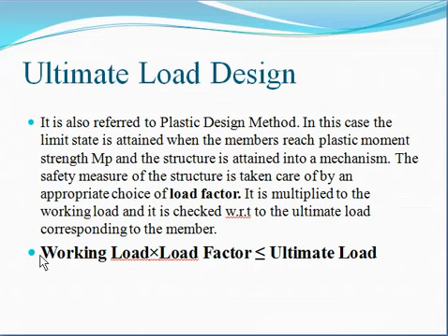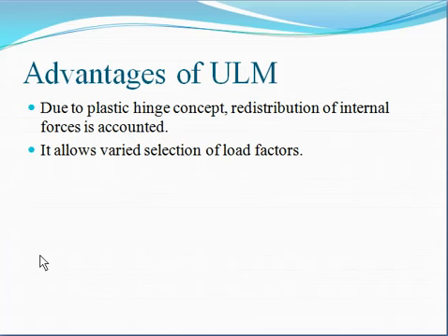In that case, the load factor is 1.3. This is all about the ultimate load method or ultimate load design. Now we will see the advantage of this method. Here, the first advantage is due to plastic hinge concept, the redistribution of the internal forces is accounted.